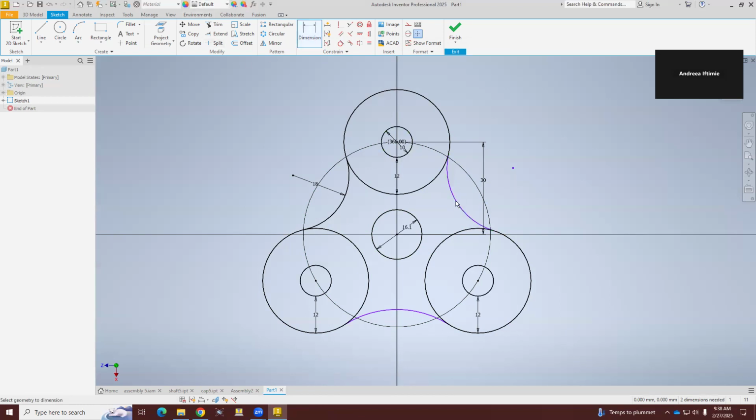Okay, dimension. See, I'm not picking the diameter. Oh, there you go. If you have the little circle with the arrow, that's going to be the diameter. This is 21. I want to put it to 18. So click 18. Going to do the same thing to this one. Oh, this one was 30. Click down 18 and my fidget looks really nice all of a sudden, right?